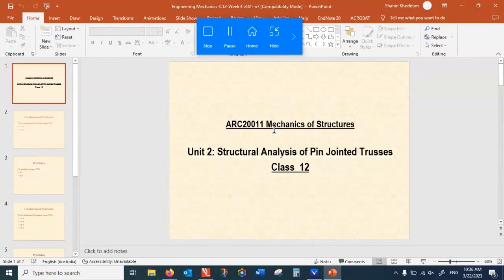So yes, that's a very efficient design. The reason is it uses the minimum amount of the material and the ratio of the strength to the weight is quite high because truss structure is hollow. It only uses material where it is needed. If you would have wanted to construct something from solid structure, that would be way more expensive, more using material. So that's the justification of why trusses are so important.